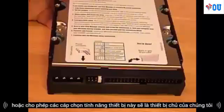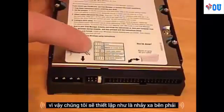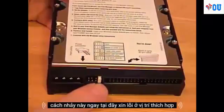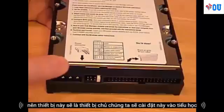This device is going to be our master device. So we're going to set it as the far right jumper. This white jumper right here is already in the proper location. So this device will be the master device. We're going to install this on the primary controller.